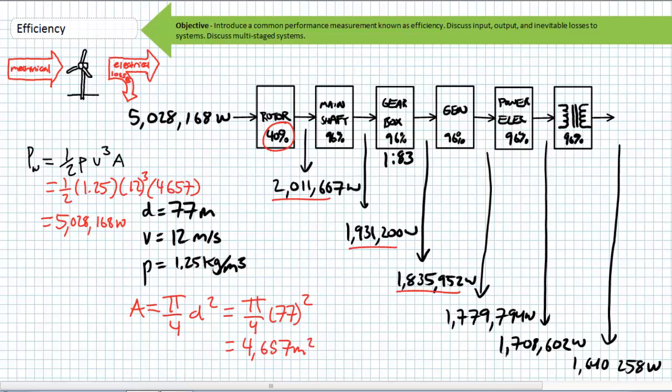high-speed shaft combination. This generator high-speed shaft combination also has an efficiency rating of 96%, taking into account misalignment between the high-speed shaft and the coupling, perhaps friction and heat. This 1.8 megawatt input is reduced to a 1.78 megawatt output.